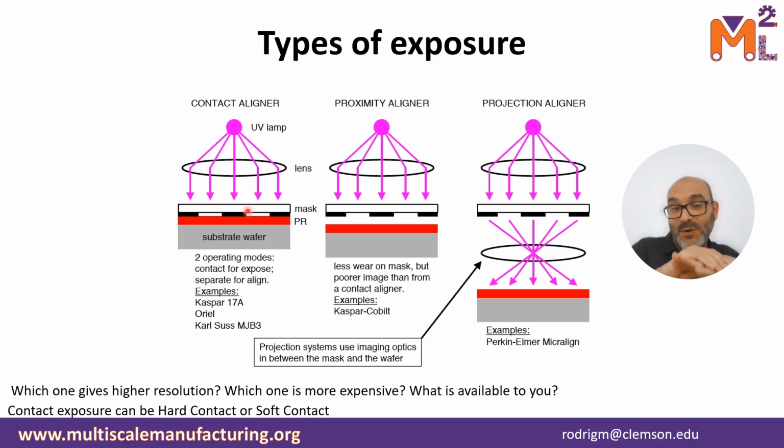If you still have solvent in your photoresist, that photoresist will still be sticky. So once you bring them into contact, it will be a little bit of a disaster and a whole lot of cleaning that you will have to do, right? So be careful that you don't have that solvent anymore, right?